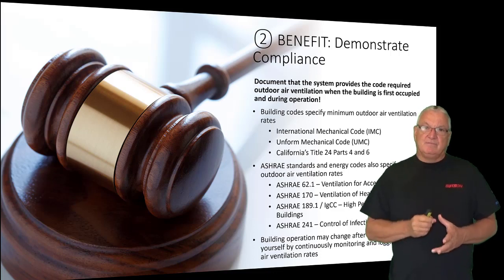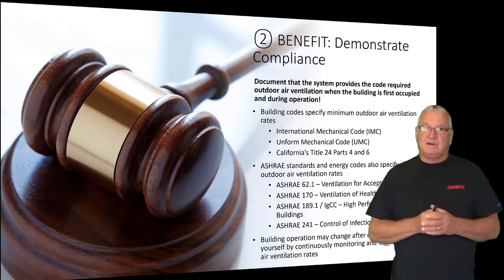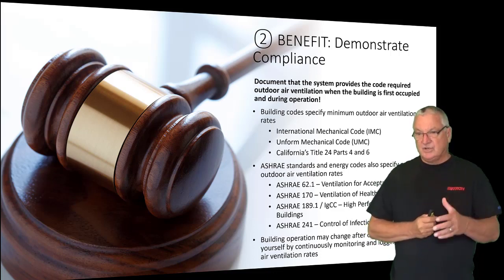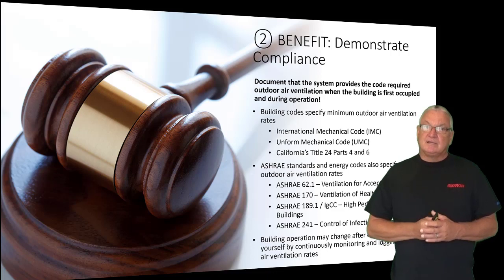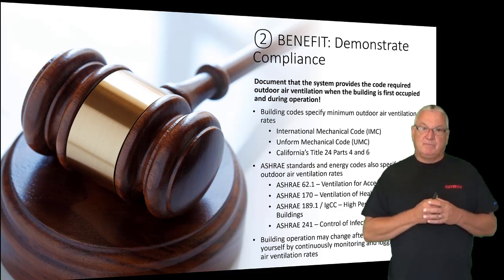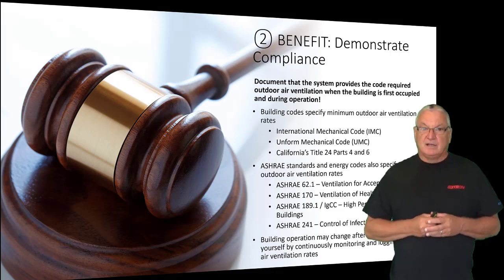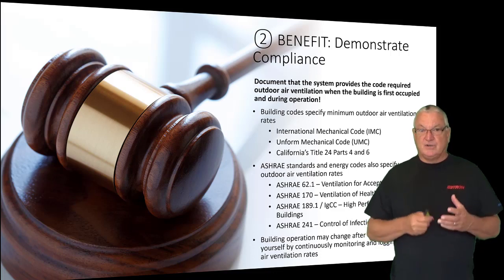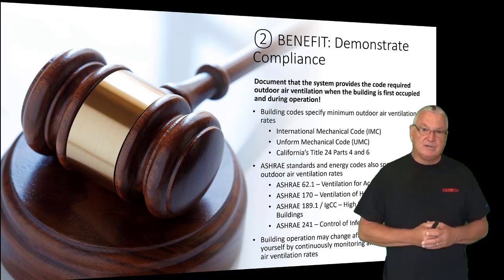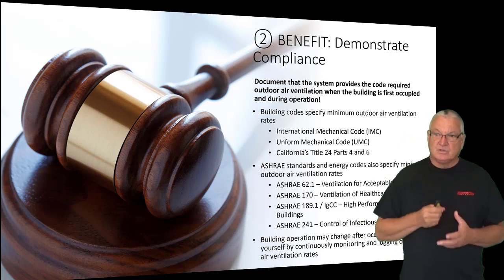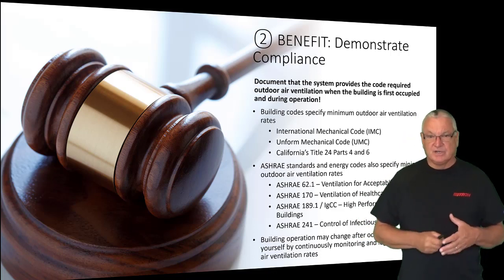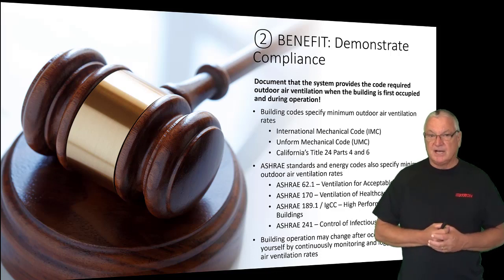The big thing for me that I want to make sure that I impress upon everybody is that it's one thing to show that you've complied with the code required ventilation when the building is first occupied. It's another thing to be able to show that the building has provided the code required ventilation or more during operation, because when you get into these buildings, a lot of times the owners will change the way the building operates, or the control people will change the way the building operates.